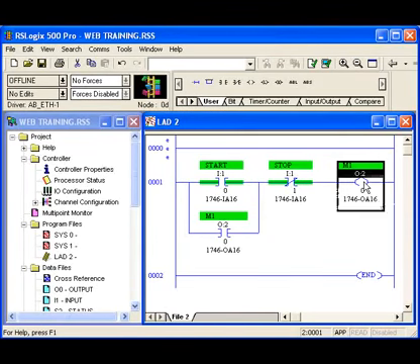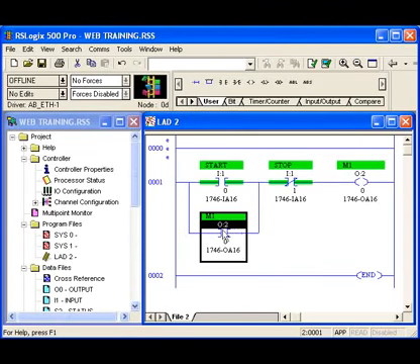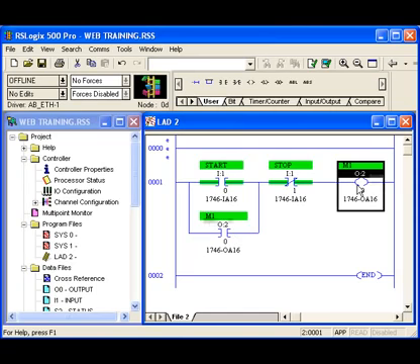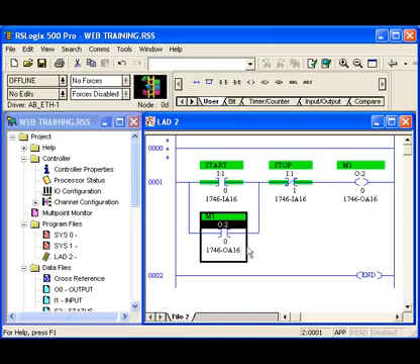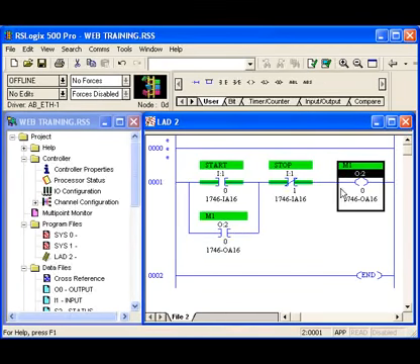So that's the power of the PLC, and that's what an internal coil is. It doesn't really have any real-world action happening on it. It's just a representation of as if you had a contact coming off this coil here, and we're able to use it in the program. Now, one very important thing is you do not use multiple outputs in a program, and we'll get into more detail on why later. Some processors will not even allow you to do that.